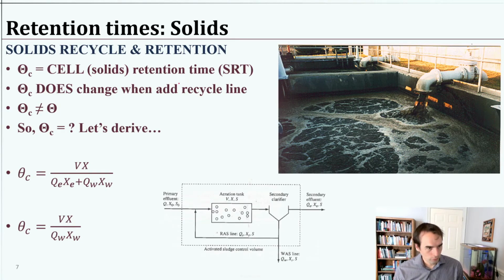Okay, so our solids retention time is going to change based on the recycle. So we need an equation to understand this, and it's not going to be the same as the hydraulic retention time if we have recycle. If we did not have any recycle, it would be just the same because it's a V over Q system.